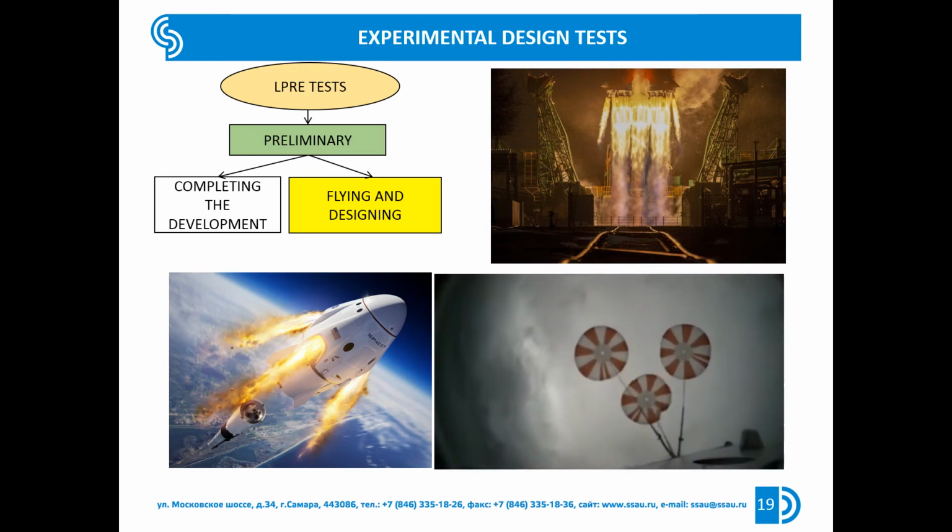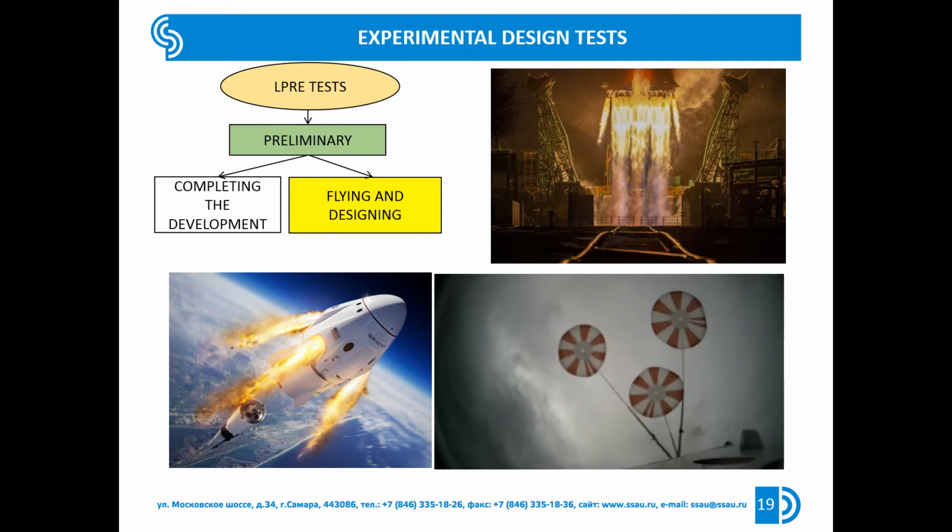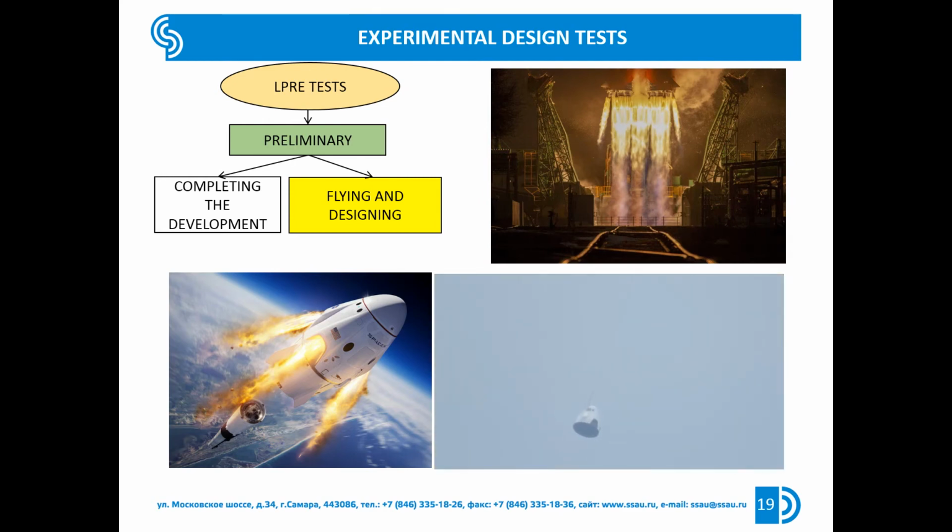A full analysis is performed after decoding and assessing the reliability of the telemetry information. As a result, the main characteristics of the LPRE and transient mode parameters are determined, including startup and shutdown, actual vibration overloads in individual points of the LPRE, and the level of the pressure pulsations in the fuel lines, thermal characteristics of design elements in various operating modes.